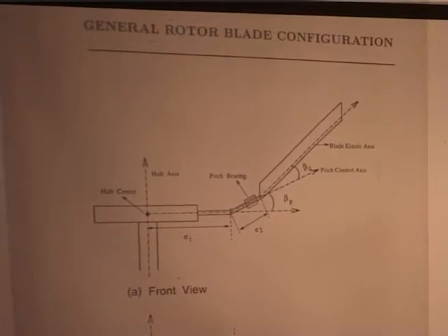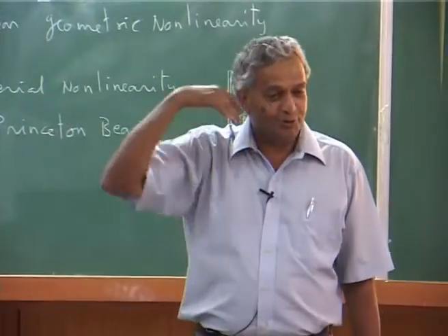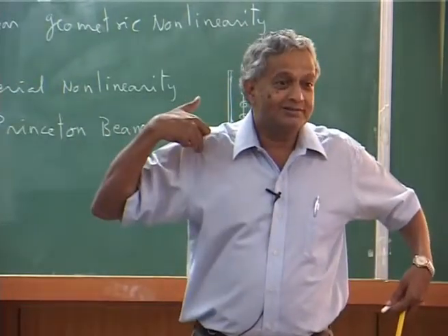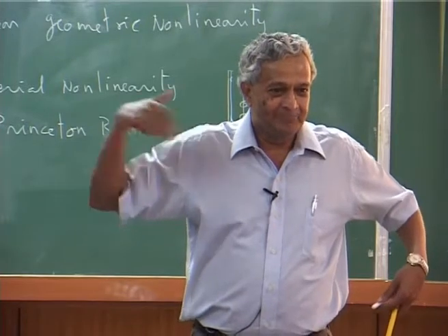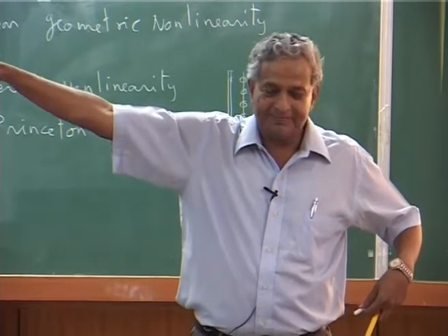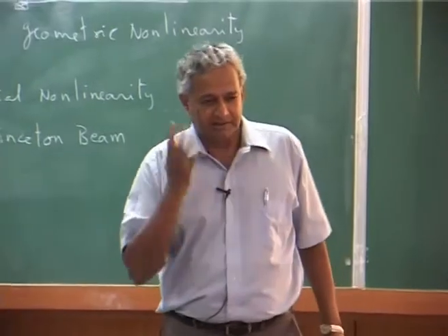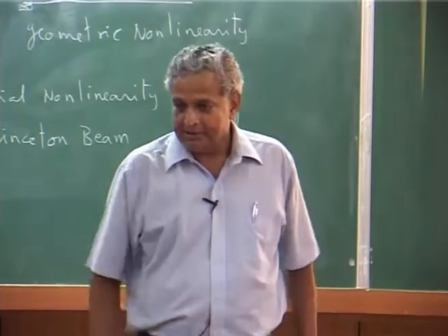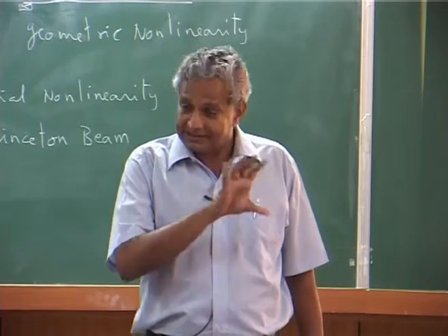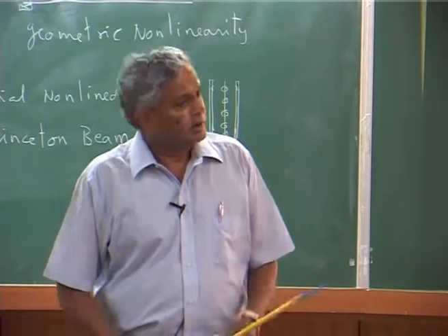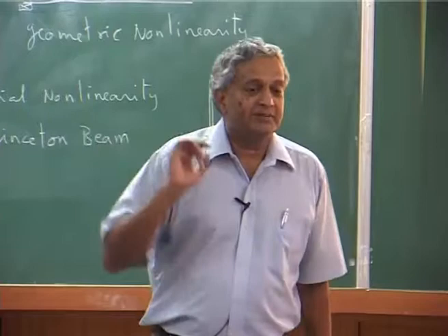See, what will happen is aerodynamic load tries to take it up, centrifugal load tries to bring it down, okay, and there is an equilibrium. Suppose if your rotor blade is already kept at the equilibrium angle, there is no root stress. You follow what I am saying? That is why that is given, that pre-cone, relieving root moment in the blade. Otherwise, you have to make the root section a little thicker. But it will also transfer as a moment to the flap hinge. It will come, no, but elastic deformation.